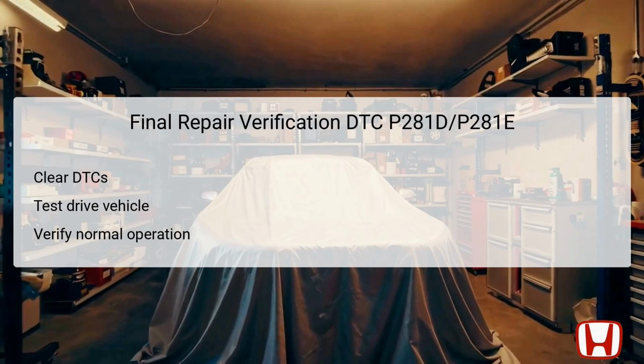Begin by clearing any outstanding DTCs using the Auto Diagnostics System, HDS. Once cleared, undertake a test drive to put the vehicle through various conditions and shifts, which will allow for any issues to surface if they still exist. Pay close attention to the vehicle's shifting performance during the test drive. It should ideally shift smoothly without any harshness.